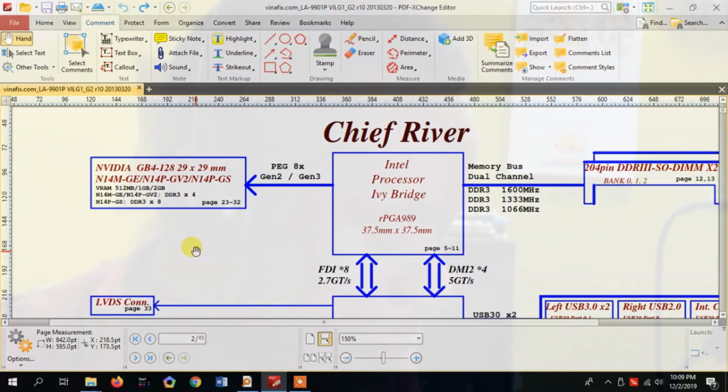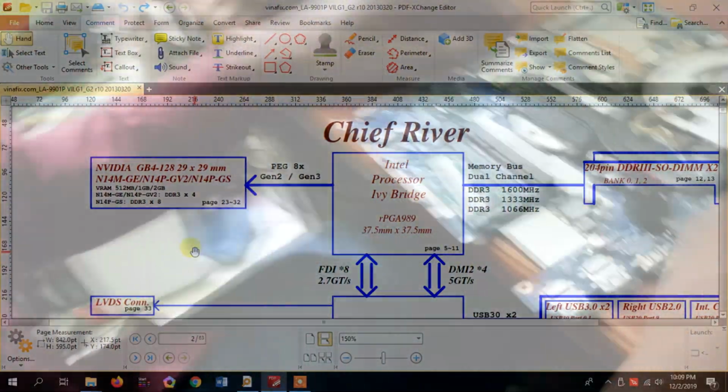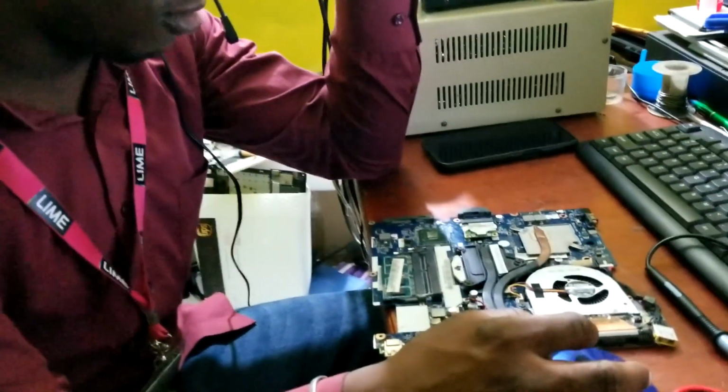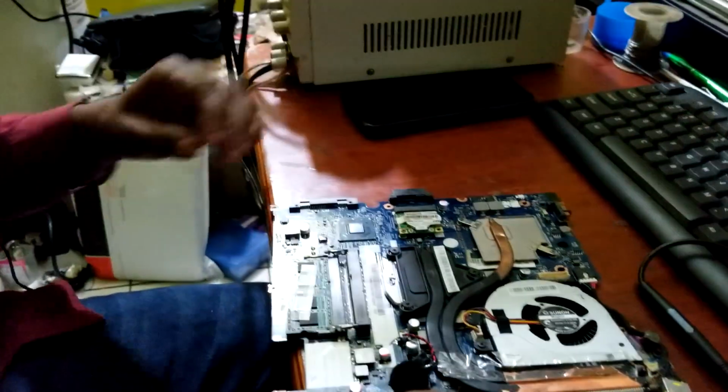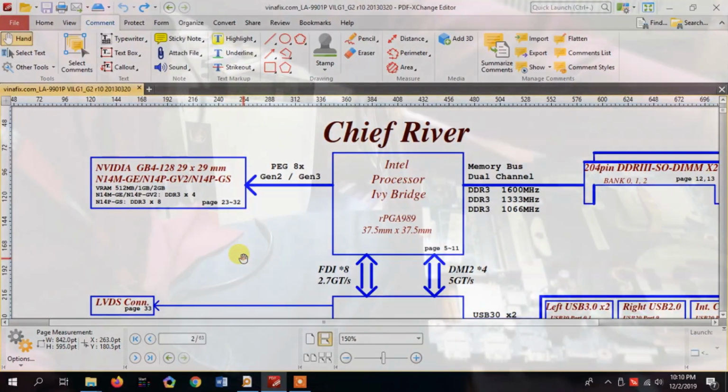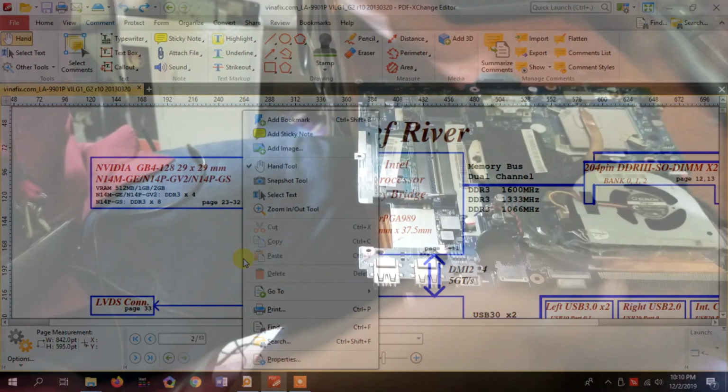But the focus is on RAM. After the CPU gets its host reset signal, how do we check and confirm that the RAM and the CPU have passed and the code has been run? So let's start. I will use the oscilloscope mostly, and maybe use the multimeter just for voltage testing. This is a Fluke.